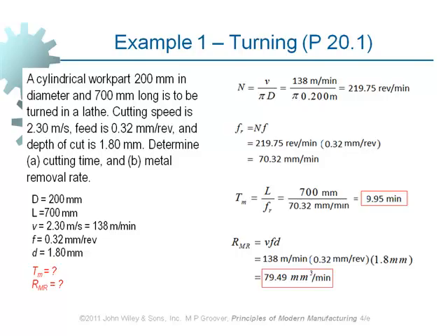Okay, now we are familiar with basic machining parameters, cutting speed, spindle speed. Do not confuse cutting speed with spindle speed. This happens very often in the workshop environment. When students are doing the task, they often confuse cutting speed with spindle speed, which is totally different. And when I ask them to write the report, they make the same mistake.